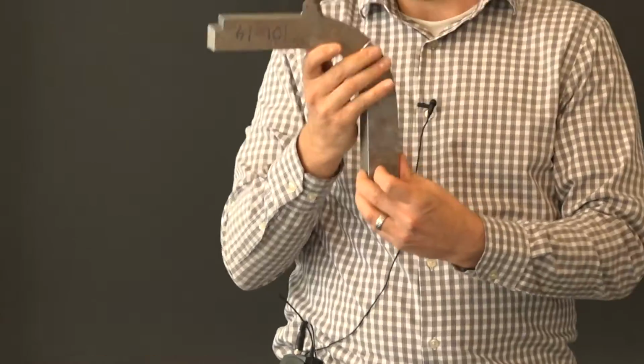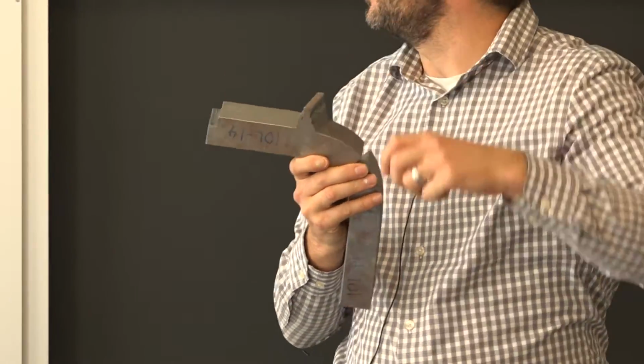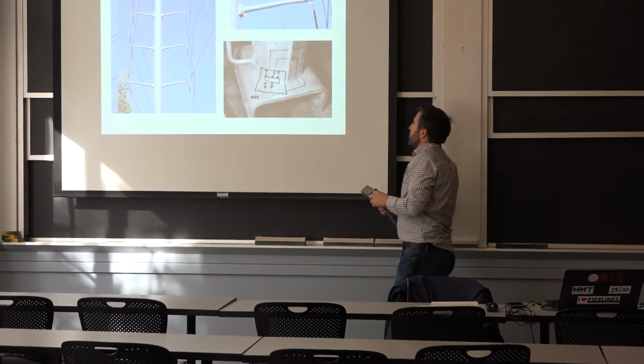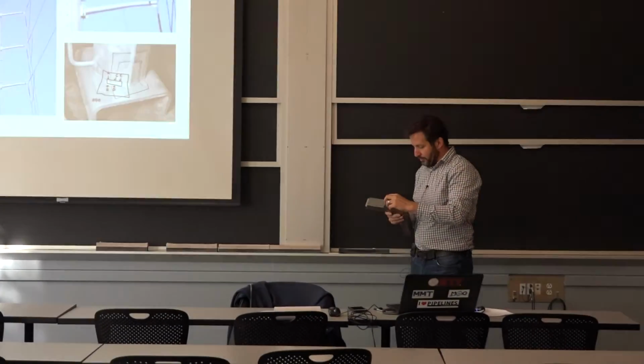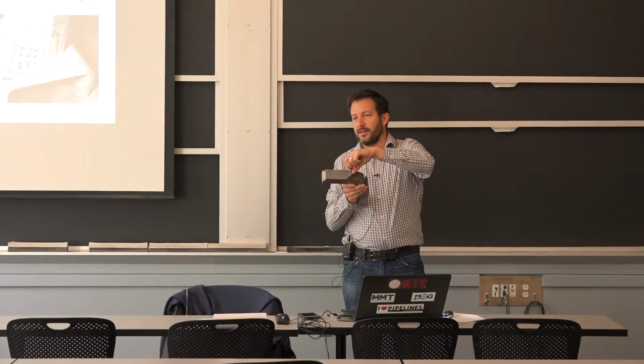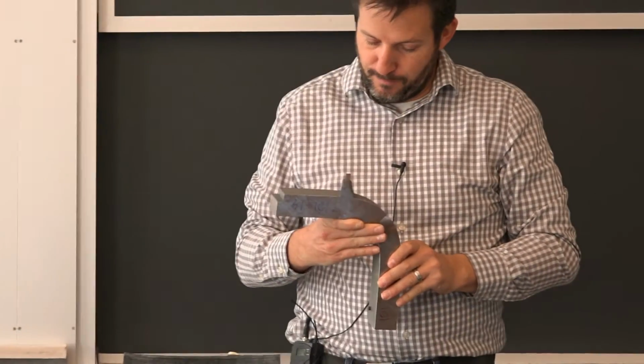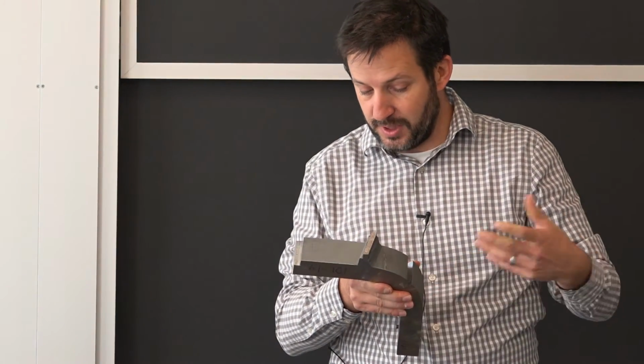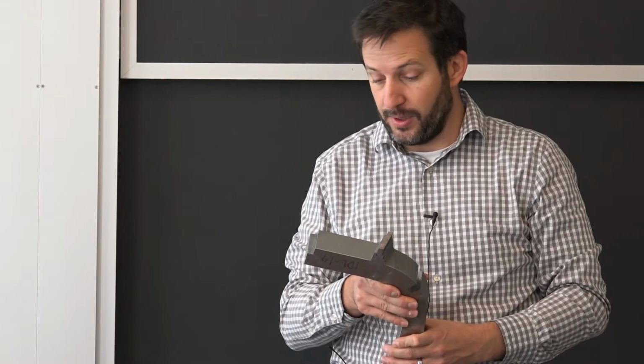It's about 1.5 inches. And the tube, the big hexagonal or octagonal tapered tube, is only this thick, 1/4 inch. And the most efficient way to connect the two together, including because of tolerances, is welding.